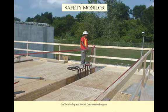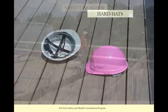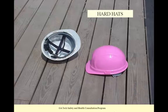A safety monitor is an employee who is designated as a competent person capable of recognizing fall hazards, who has no other responsibilities or job functions when acting in this capacity. Hard hats should always be used when there is the possibility that an employee might be exposed to a falling object. Remember, hard hats must be worn in accordance with the manufacturer's guidelines in order to provide the best protection.